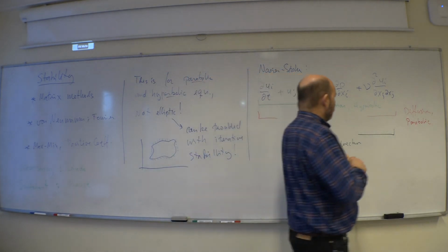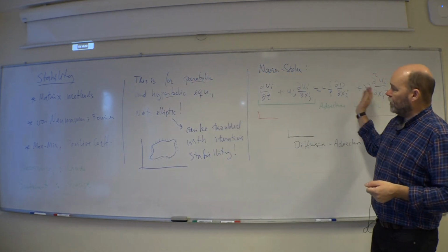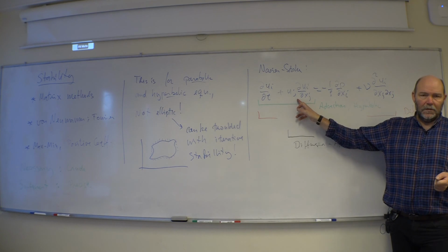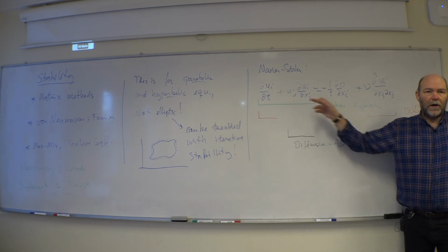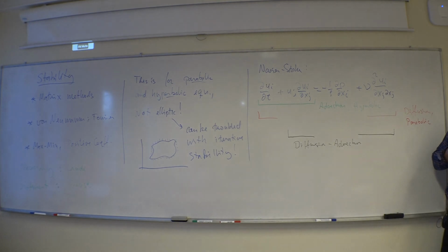And here, since we know that the entire equation system is nonlinear, you can't really get the precise one either way. So you might risk that the delta t criteria you find, the problem might be stable if you choose a smaller one, and the problem might be unstable even though you are inside the limit.